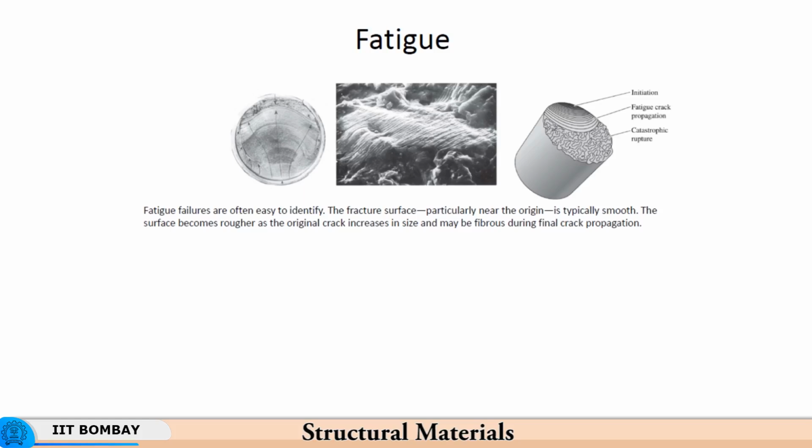Well, in the case of rotating bending type of fatigue of shafts, let us say you have a power shaft which is rotating under load, there you will find that the loading changes not only from tension to 0, but it goes into the compressive direction as well. So you have basically a loading characteristic where the load alternates between tension and compression. So it all depends on the situation in which the workpiece is working.